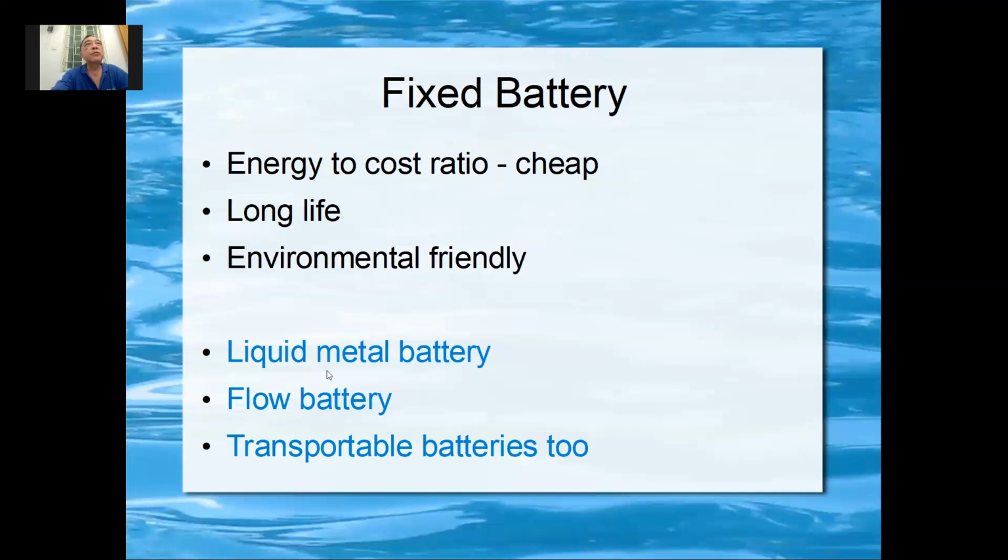Some of these batteries are like the liquid metal battery or the flow battery. Some are transportable batteries also, like you can use lithium titanate or lithium iron phosphate, and make it very, very big, the size of a container, and put it on the floor. It can be used. But of course, if you want to use lithium ion, you must be very careful. Otherwise, you catch fire, your whole container burns. And the neighbors will complain about the smoke, that it's poisonous.